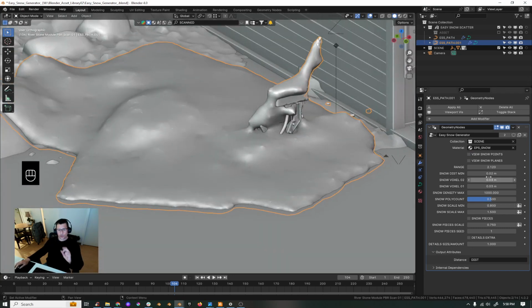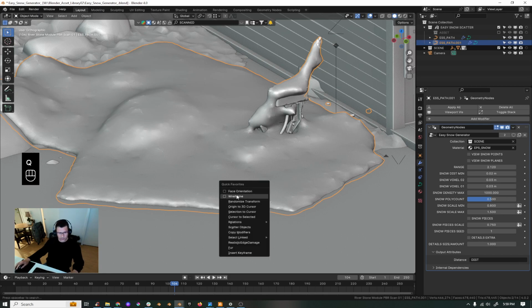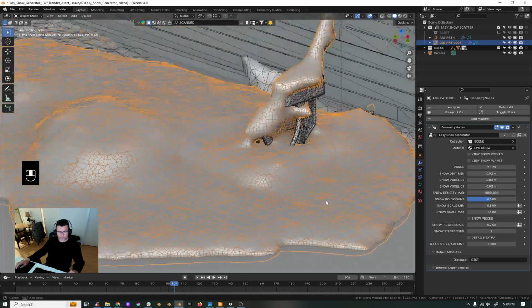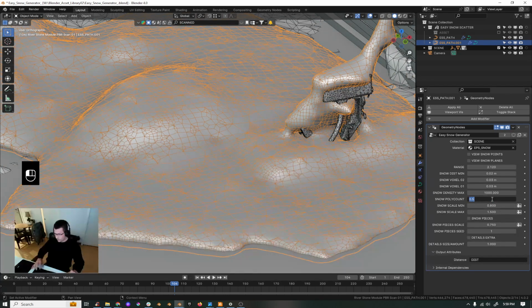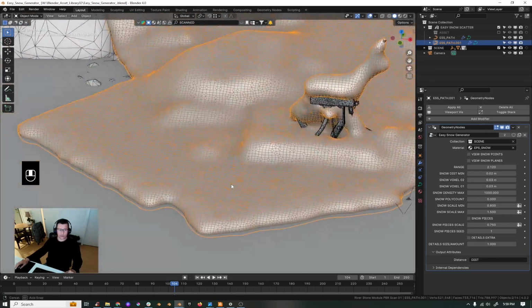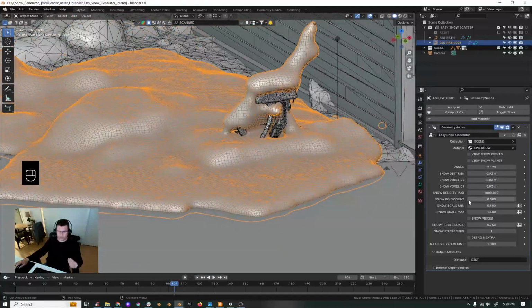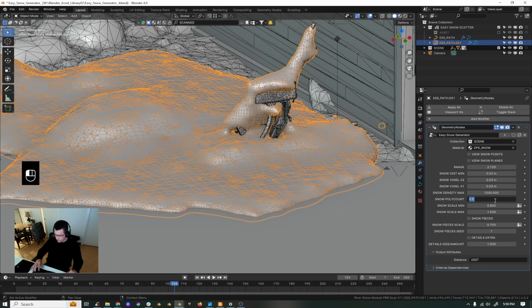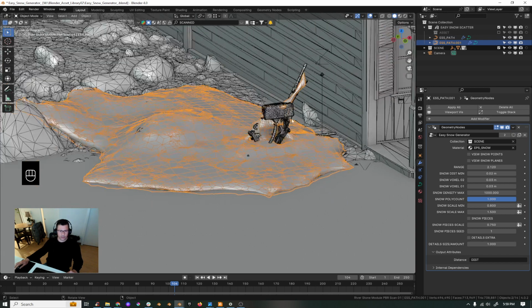Okay, so we have those settings that all have to do with the quality of your snow. Okay, right now the poly count of your snow is pretty low. Okay, and the reason is because of this guy. If you leave it 0, the snow will be totally quantified and it will have more resolution, but you don't need that and you don't want that. So maybe, depending on what you want to achieve, but for now I think that 0.5 is a good amount. If you leave it 1, it will be very melted, right?